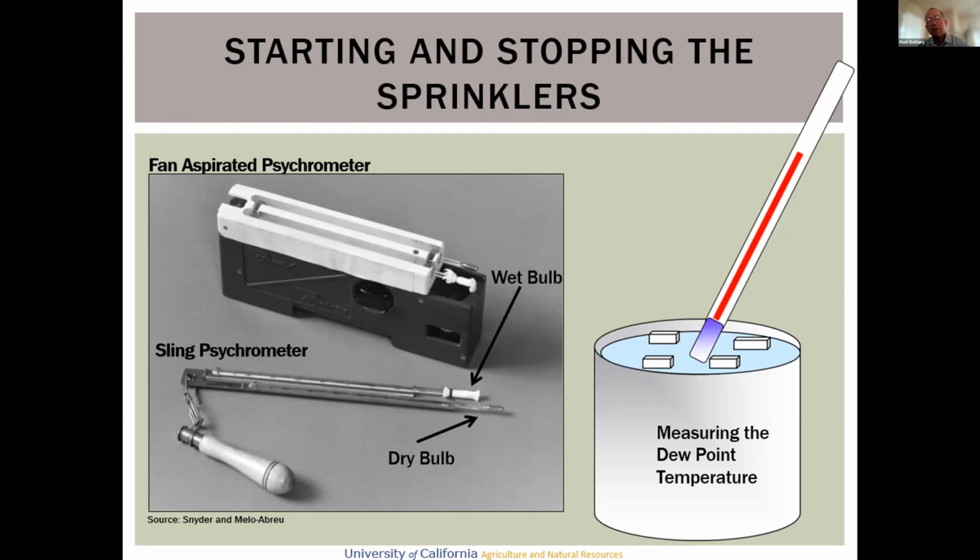The alternative to using something like this would be, let's say, a weather station or other sensor that has a humidity sensor, the air humidity, and from that we can then calculate the wet bulb temperature. The problem with that is that on weather stations, the humidity reading is one of the least accurate ones of all of them. That sensor has a lot of variability. So it's plus or minus, in some cases, 5% or more. So that can really impact the precision of the data we're getting from that reading.